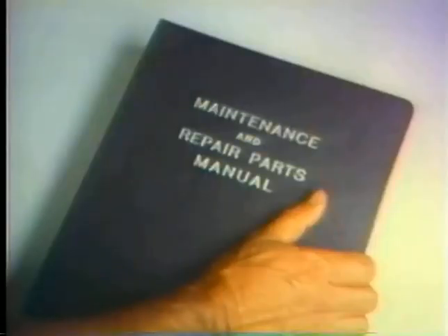If there's no pressure setting given in the manual, a good rule of thumb is 1 1/2 to 2 pounds pressure per square inch of brush seating surface. If the manual has disappeared, you could figure it out mathematically.